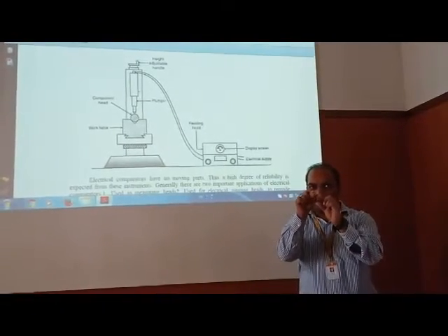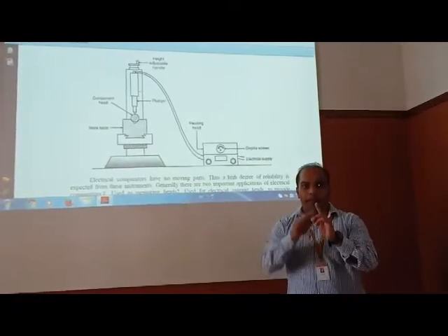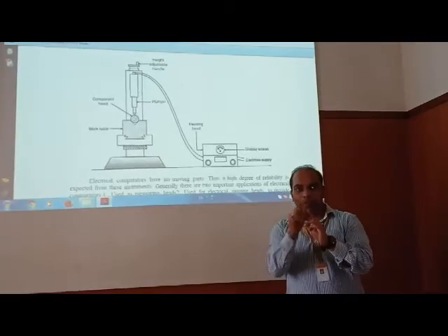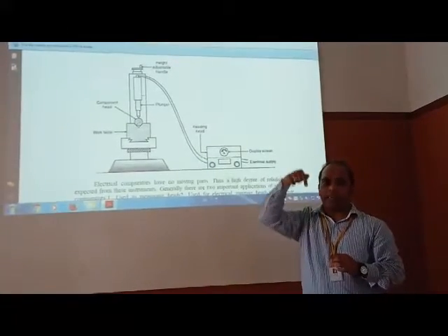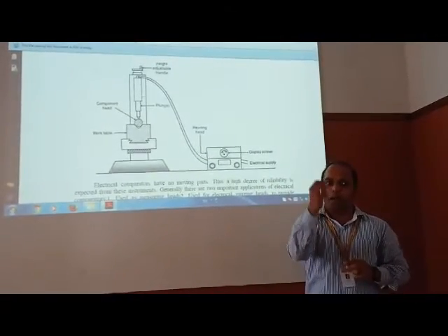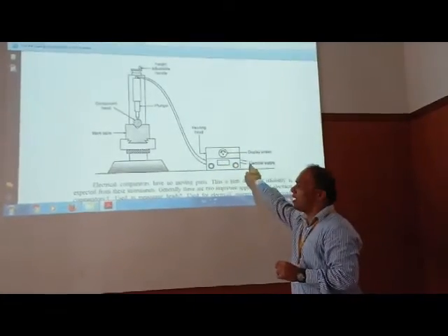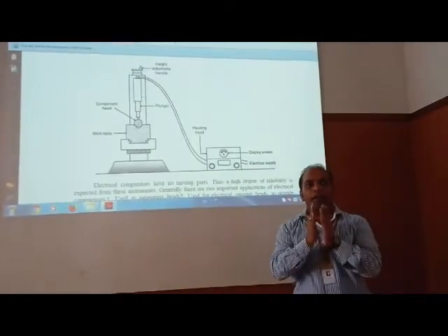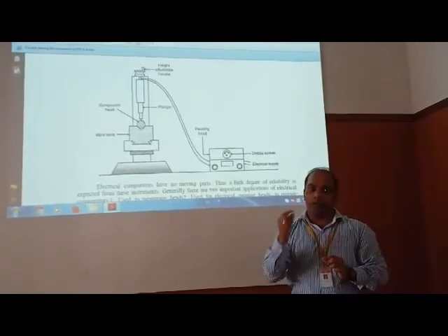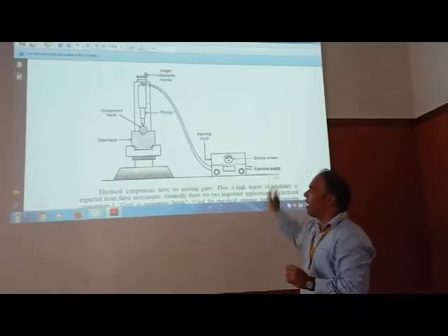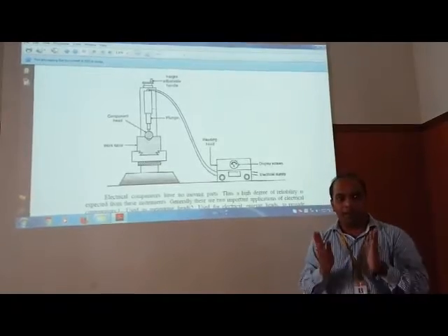Any small dimensional variation. Now the dimensional variation may occur in two forms. The very first, top, that is the crest, and bottom, that is the downside. So the plunger will record the movement. It will go plus minus, and a very small, or you can call it a minute, change will be noted and sent back to the electrical supply. Now the electrical supply unit will record the minute change and display it on the display section. So this is the working of the electrical comparator in the most simplified format. Next,